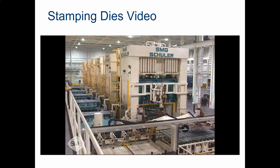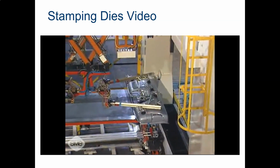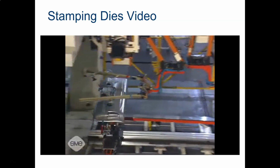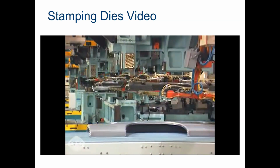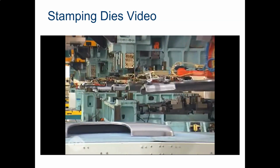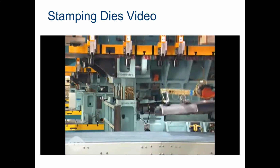With large workpieces, a tandem press line may be utilized. Parts are transferred by gripping devices from press to press, instead of within a single die. Each press within the tandem line holds its own tooling and performs specific operations to form, trim, and pierce the part.